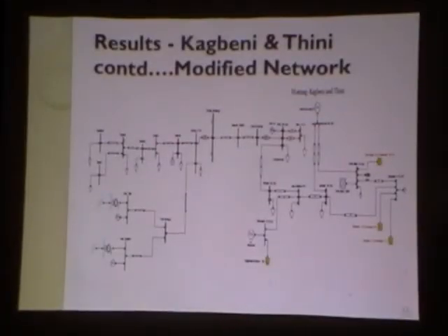And again, from this figure, we see that the power system loss for the network continuously increases up to 6.99% while penetrating to 6.88 megawatt, a loss increase of more than 1.2%. So we cannot go for this. That's why this system is remodeled to get the highest penetration level in that corridor.